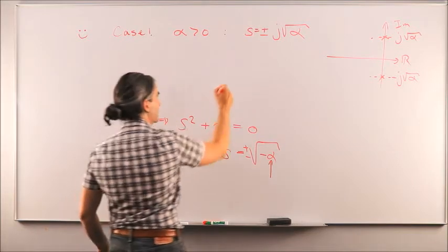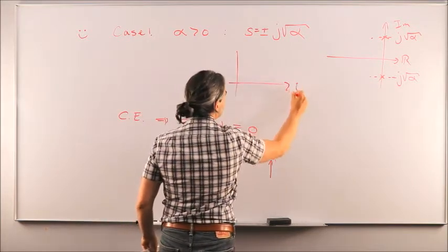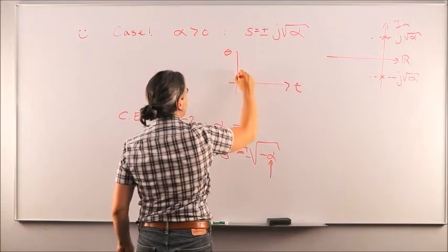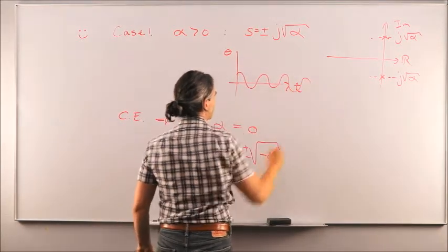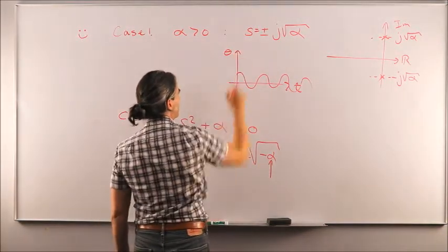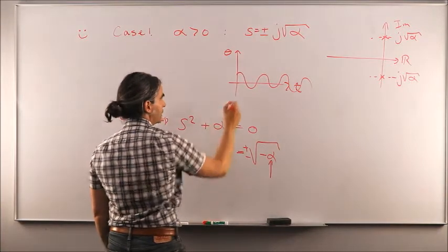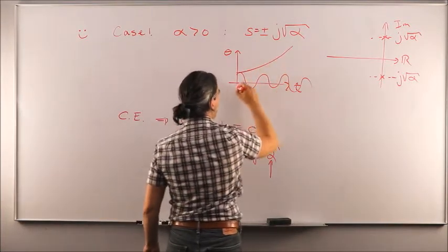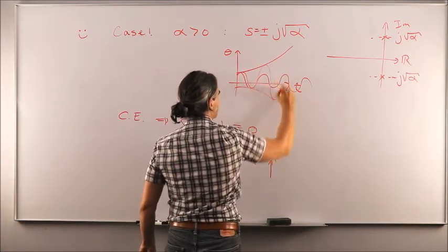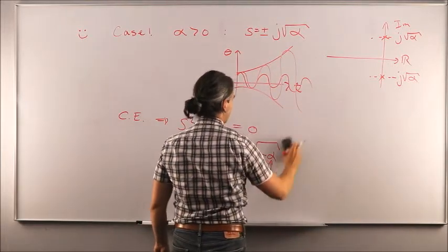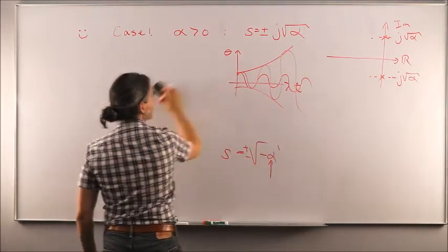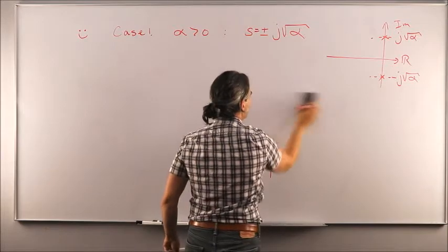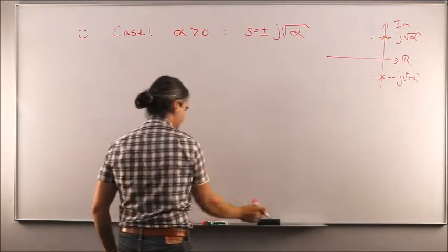The pitch will just keep oscillating. Okay, if this is pitch angle, you would see that kind of motion. But it's not ideal, but it's way better than having something which would grow with time, okay? So stable behavior is always good for passive stabilization techniques.